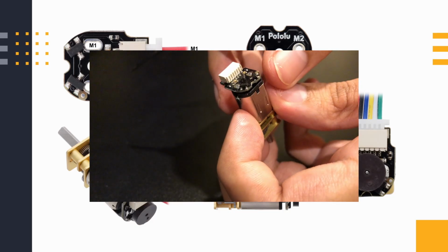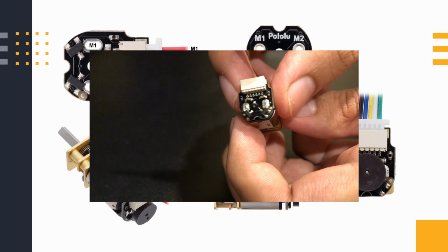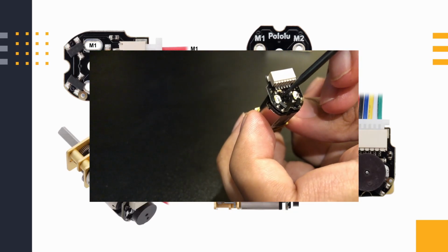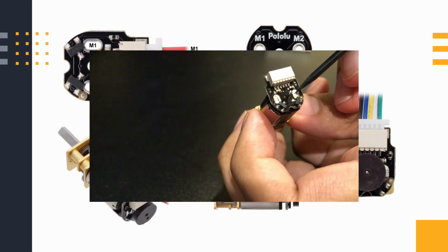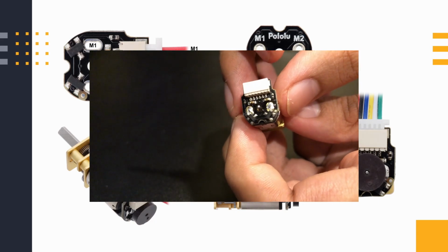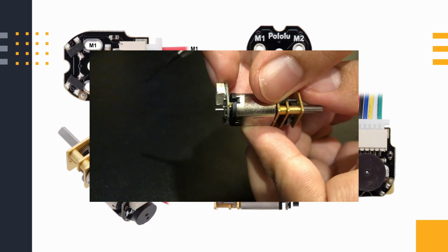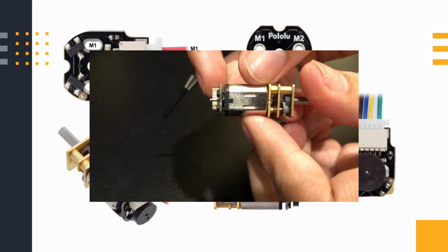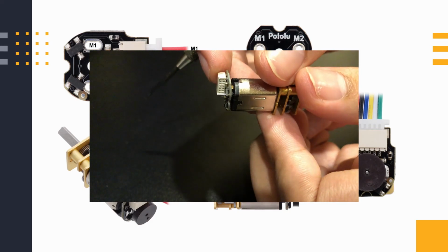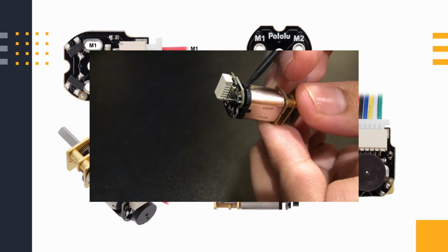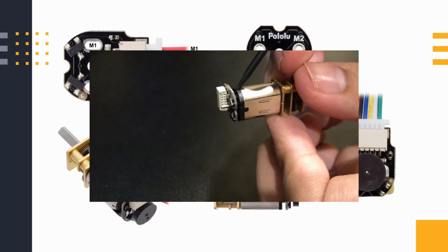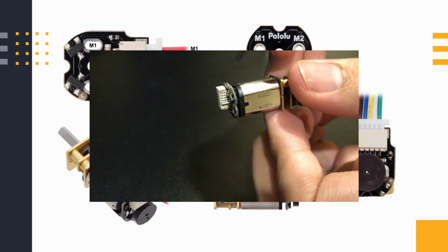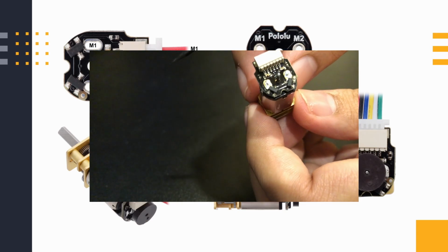This hole right here. This hole and that hole. That's where the power terminals are for the motor. That's what connects to the brushes, and basically you place those two prongs into these two holes and then you solder them. So this is now secured in place.